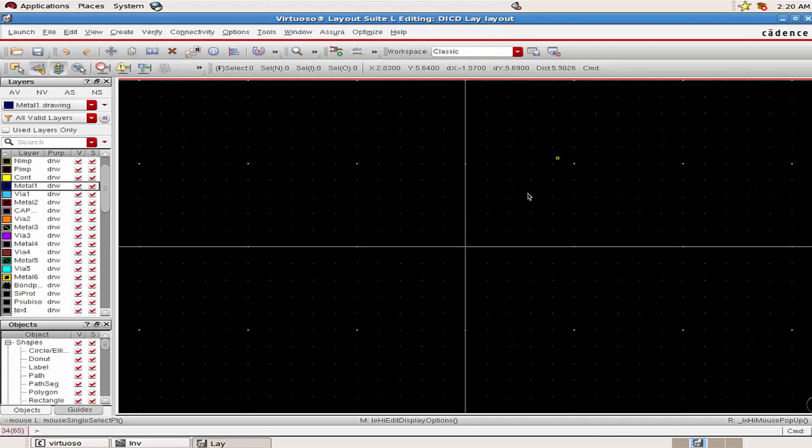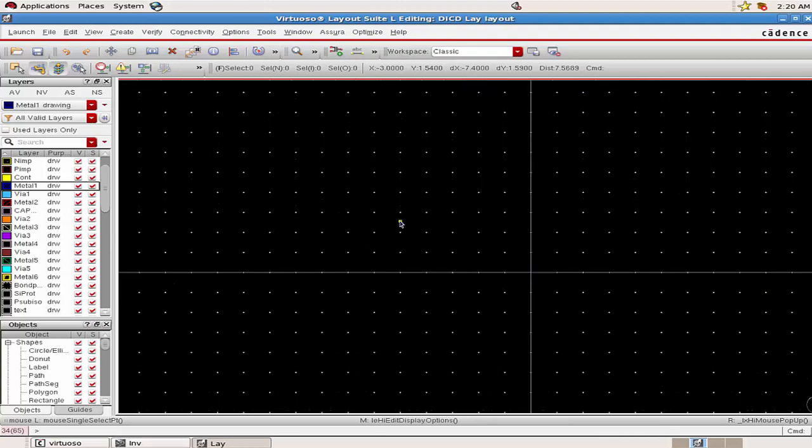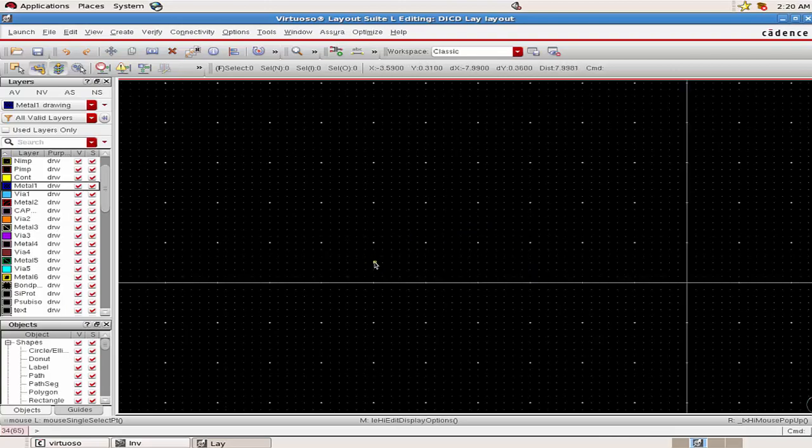Now we have gone through this options menu and clicked OK, but we can't see any change in this screen with respect to the dots. To make this effective, scroll your mouse button back and forth, and you will see suddenly the dots have changed, which means we have increased the dot intensities. When you zoom in, you can see that within the major dots there are 6 small dots. This is what I was showing through this option display.